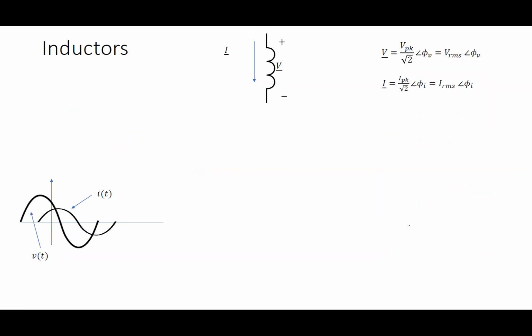All right, so inductors, same story, right? What's the impedance for this one? J omega L. Everybody wants to write LW, but it's omega. The Greeks don't get credit for a whole lot. They deserve it. Z equals J omega L. Now this one is also complex. It has no real part, but it has an imaginary part. I can write it in magnitude-angle form as well. What's the magnitude? Omega L.